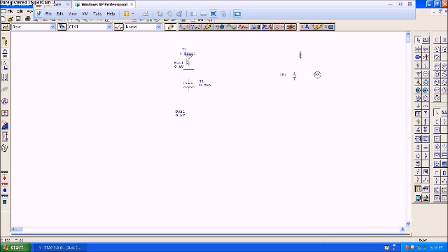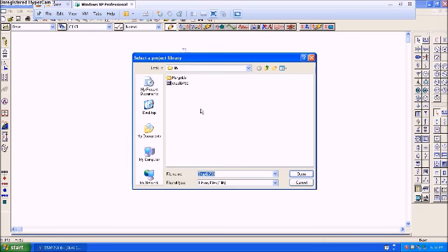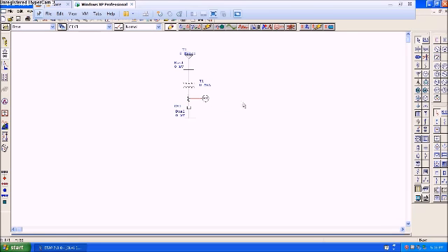Now, how to connect these things? We are connecting just by joining these two. To connect the circuit breaker, we can do it like this. But for connecting the relay, we have to give a current transformer. Now as you can see, we have just designed the model circuit. For inserting the values, we can double click on them and we can show the values.